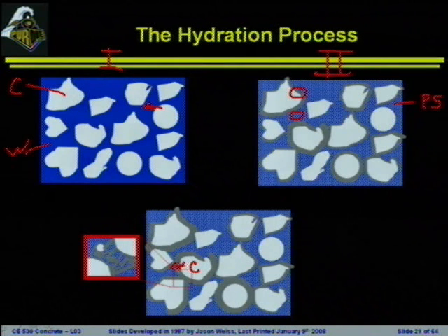At some point, these particles are going to start interacting with each other. They're going to start sticking together, and that's typically what we refer to as set. And this is going to define when the material goes from a fluid system into a solid system. Over time, this reaction is going to continue to go on, and you're going to see this system filling in more. You're going to see this open space being reduced, and the bonds are going to be developing more and more between those particles.